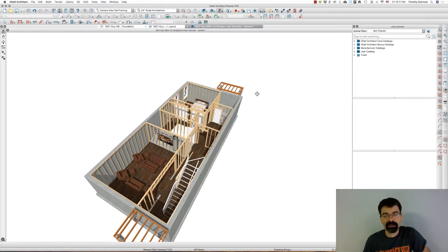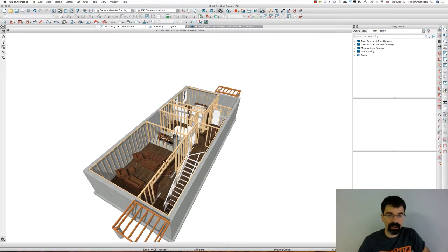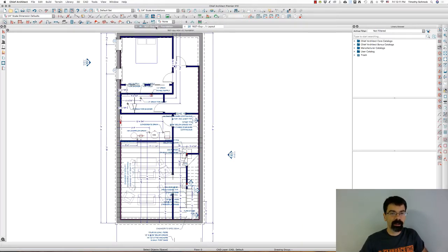Remember last week where I changed wall layers and object layers to be future proposed basement. I designed an unfinished basement out. And so I turned certain walls and objects into a future layer so that they did not appear on my plans. But as I'm going through, you'll notice here also the framing got built in these layers. So what I'm going to do is walk through how I change these to not have framing.